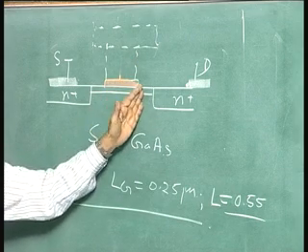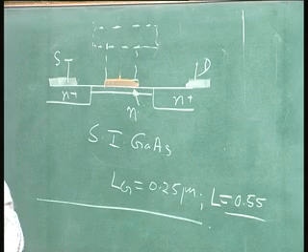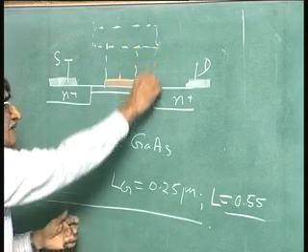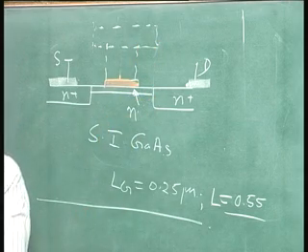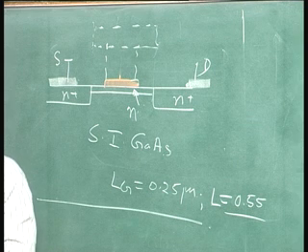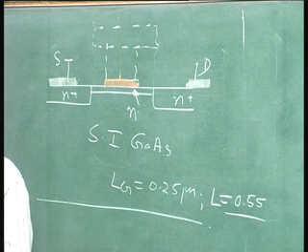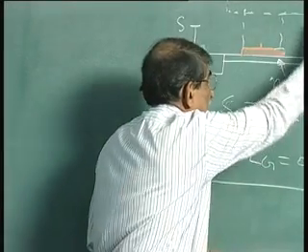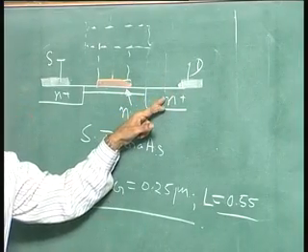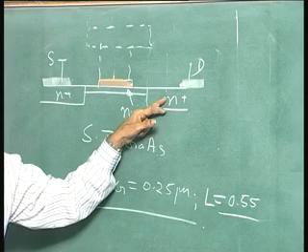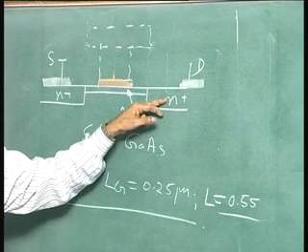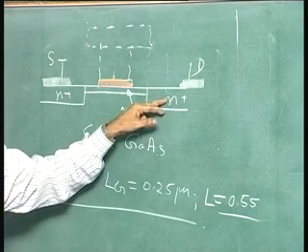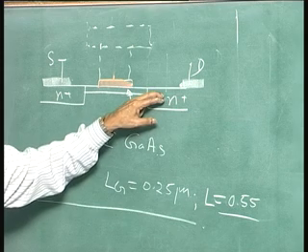Now, when you bring this closer and closer, there are two things. One important thing that happens is, it is not as if these implanted atoms just rest vertically like that. Okay. This is a statistical phenomenon. When implanted, where it goes and lands is a statistical phenomenon. When you implant like this here, the ions which come there get neutralized, of course, when they land in the atom, because the electrons come from the back door, from the other contact. So, when it lands, it is neutral after it landed.